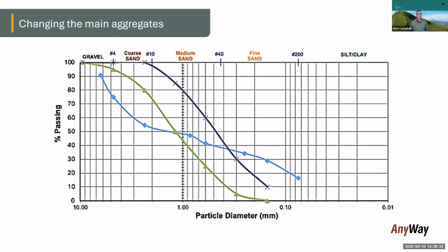The fineness of the material is outside of the window that we typically use for concrete. An aggregate that would be used in concrete would be somewhere in between, for those of you that aren't colorblind, the green and the purple line, or the one with triangles or X's. And the typical gradation that we used from our quarry waste products is the blue line with the squares in it. You can see that there's no way this material would be permissible to be used within a concrete system.